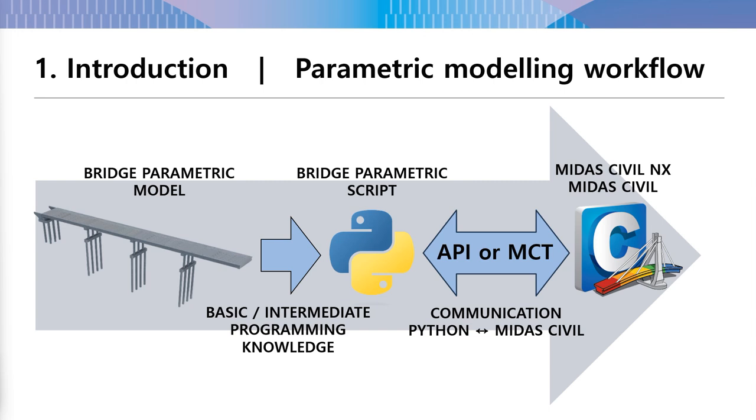Inside each of these groups, we define a parametric bridge model. We see inside these groups of, for example, 20 models, what the differences are between those bridges. Is the difference pile length? Then we choose the pile length to be a parameter for our parametric model. Maybe the difference is pier height, or maybe the difference is main girder cross-section height. So these are the definitions of our parameters for our bridge parametric model. Then this is something like an idea of what we want our parametric bridge script to do for us.